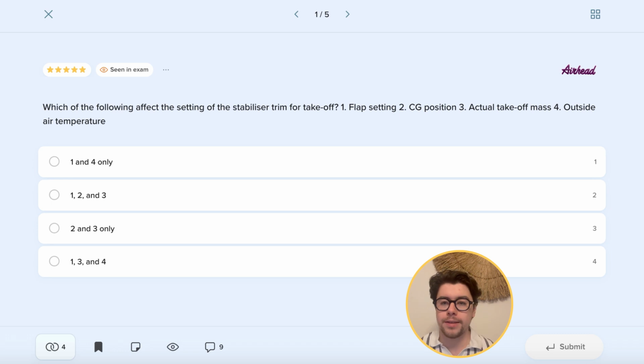before you would like it to do so. And in order to set this and prepare everything, you'll be given a load sheet from the loadmaster after the aircraft is filled with passengers, and this will have all the loads in there, and as well it will have the recommended setting for the horizontal stabilizer trim.